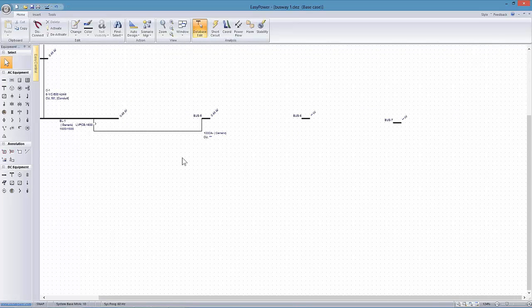Again, I've made the decision that I want my drops to consolidate the loads that are within 50 feet each side of this. So this drop will take care of everything between the breaker and this first 50-foot length. And then the next busway, I'm going to connect between this drop point and the next one out, and this will be 100 feet. In reality, I probably want to point these down so I can see my connection points.